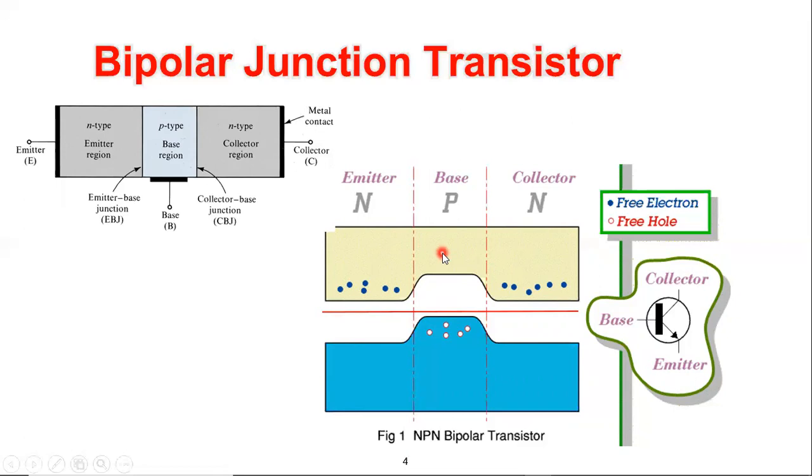We also have to remember a very important note, which we will use until the end of this lecture. The NPN BJT is simply two PN junctions. If you make a clear cut here, if you divide this junction in two, you will find an NP junction and a PN junction. So it's simply two diodes. Here we have an emitter-base junction, and we have a base-collector junction. So from now until the end of the lecture, we will deal with our BJT as two connected diodes, two connected NP and PN junctions.